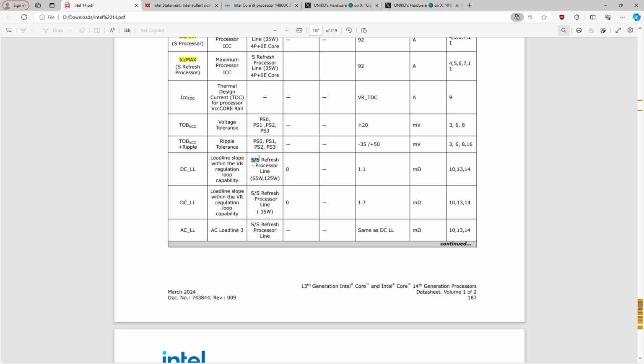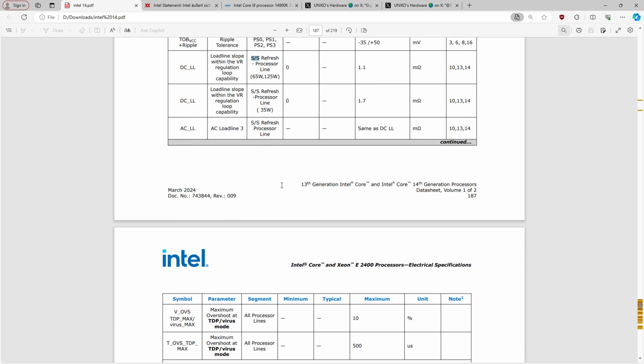Right, and this is specifically for the socketed CPUs. Even if you had a BGA, the BGA doesn't have 0 resistance and 0 inductance. It's a lot lower than a CPU socket, but it's not 0. And then, of course, you have the substrate of the CPU itself. That has some resistance and inductance, because the voltage regulator actually monitors the output voltage at the die, right?